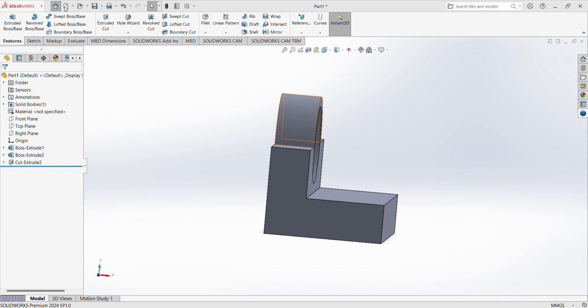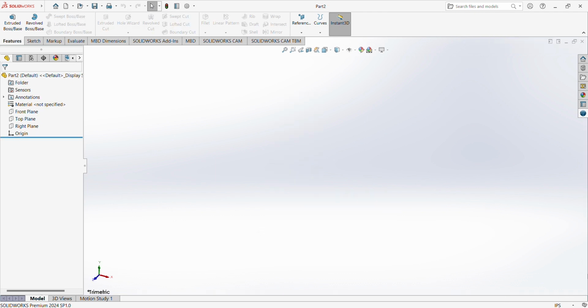or you go to new straight. Then let's just go back and go to new. Just click on new. Then select parts. Okay, so depending on the units of your dimensions, you decide on what you're going to use. Me, I'm using mmgs, so I'm changing my IPS to mmgs.